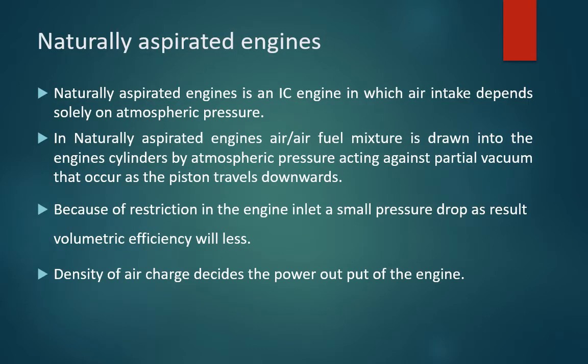When I talk about naturally aspirated engines, it means an IC engine in which air intake depends solely on atmospheric pressure. In naturally aspirated engines, air or air-fuel mixture is drawn into the engine cylinders by atmospheric pressure acting against the partial vacuum that occurs at the piston when the piston travels downwards. When the piston moves towards the bottom dead center, it creates a partial vacuum. That partial vacuum is filled, against the atmospheric pressure, by the incoming air-fuel mixture or the air inside the cylinder. Because of the restriction at the engine inlet, there is a small pressure drop. As a result, volumetric efficiency will reduce. The density of the charge decides the power output of this engine.